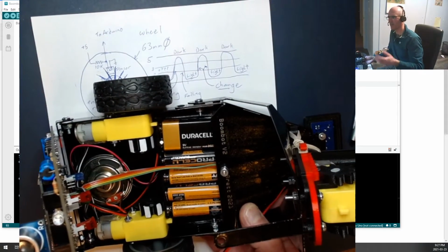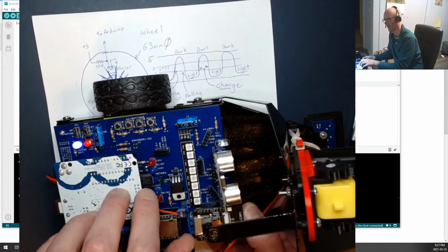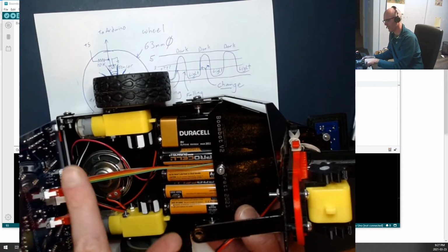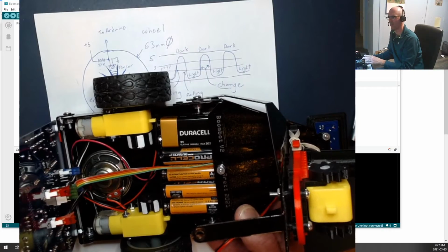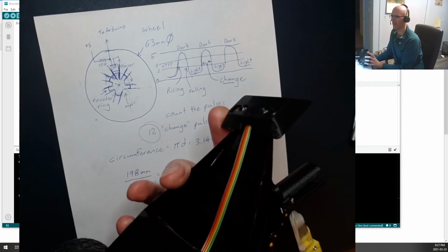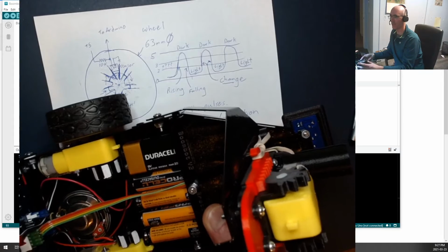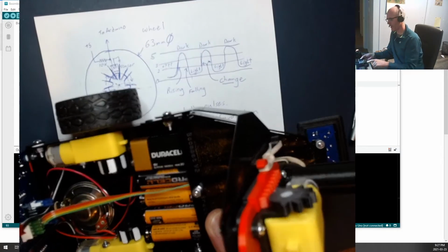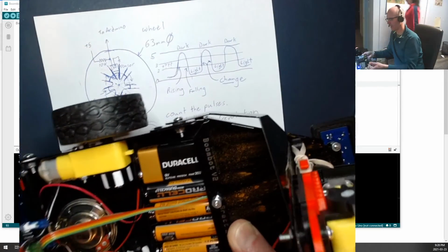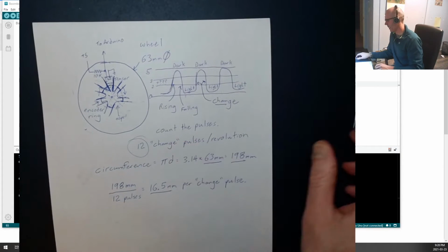Up until now, the only thing we've mentioned about them is that when you're building your robot, you don't want to hear clunk, clunk, clunk, because that flips down there, and we don't want this interfering with them. We want this sitting about 1 millimeter off the surface. After talking about the edge detectors on the front for line following, and how they work optimally at a distance of about 1 millimeter, you probably now know why we wanted these sensors to be 1 millimeter above this platform.